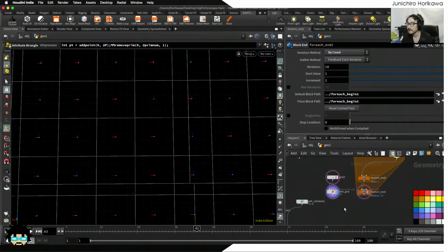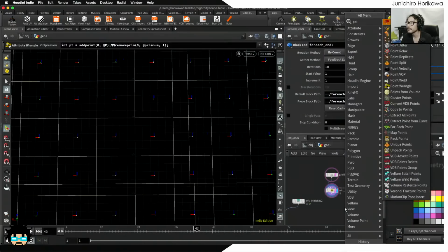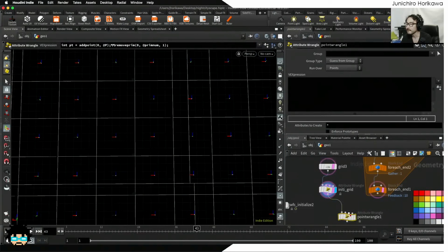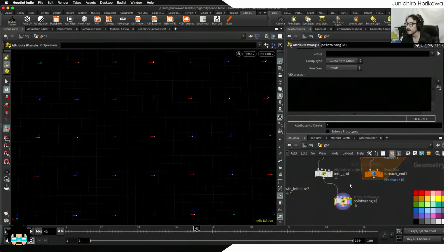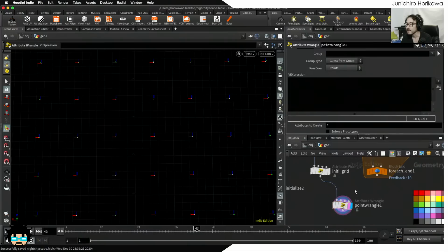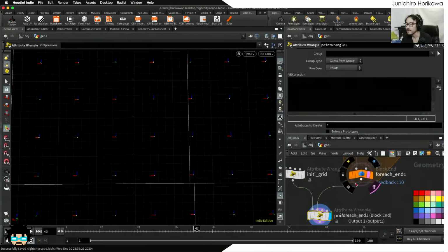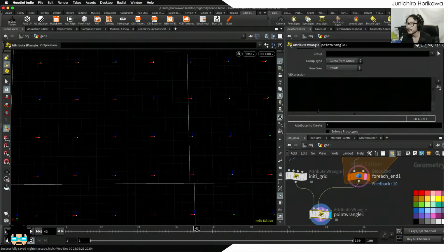Okay, so let's do a point wrangle, and this is the one that I want to convert the attributes, and this is the guide to check if there's an intersection or not. Now I know that the grid size is 1, so I need to check whether the distance between the point and the line is within 0.5. That's the goal number here.